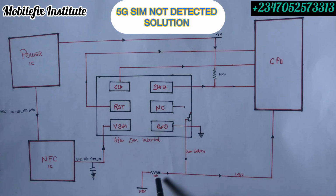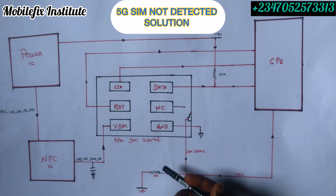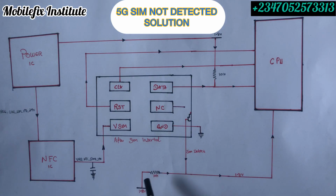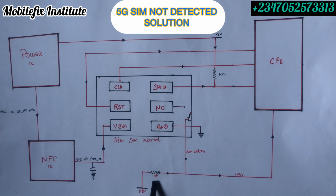Okay. Now there are other circuits that might decide to change this resistor to maybe a different value that is not 10k. So you have to work with your schematics. I'm explaining this circuit that has 10k ohms, but most of the circuits you will see will have 10k, because this is how this circuit works. So test this 10k resistor. If it's faulty, you remove this resistor and put a 10k resistor.